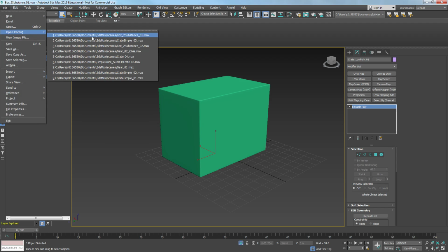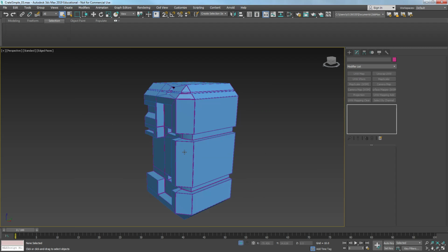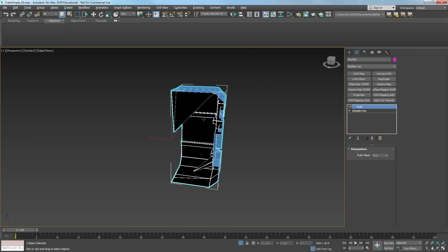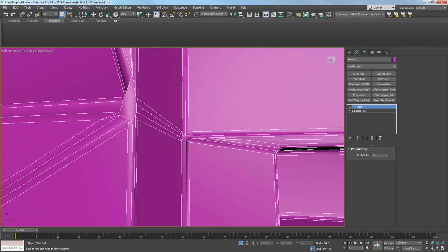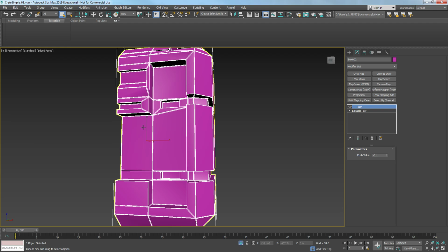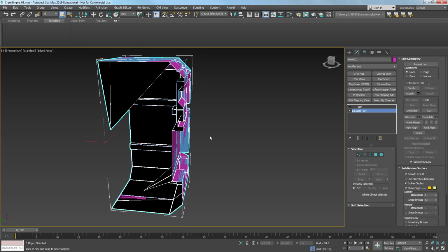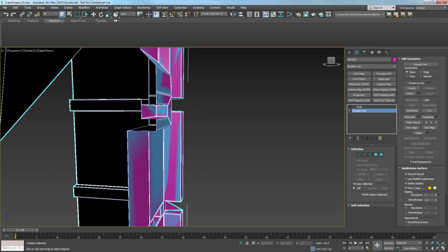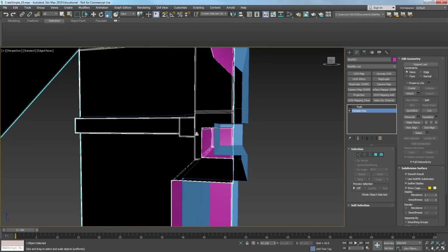Let me get in here. Let me just get this one example here real quick, and I'll show you why I want to not use different software when you want to shrink your mesh. All right, so this is my high poly mesh. All I did was add a chamfer to my low poly mesh. Now it's not effective, and that's gross, and it's going to make very bad projections. But the point I want to make is this: I don't want to scale my object to fit inside my low poly. I don't want to have this parallax right here. That's not going to give me a good projection. The low poly has to capture all the details from the high poly. And if I use scale, it's just going to create some nasty overlaps, which is not going to be effective.